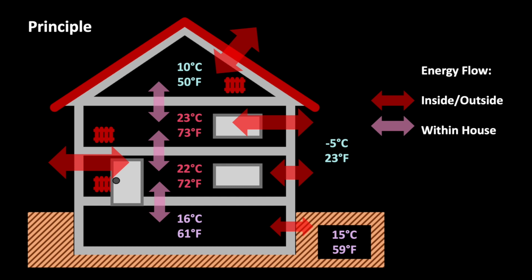We take all these heat flows into account in our calculations by considering the temperature differences, the thermal conductivity coefficients, and the size of the interfacing areas between the spaces. As already mentioned, this works not only for heating but also for air conditioning.